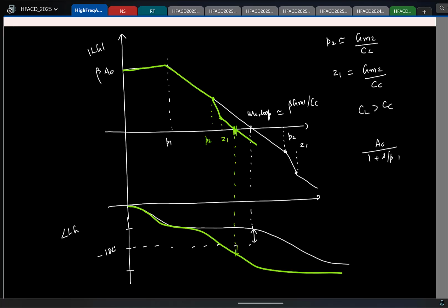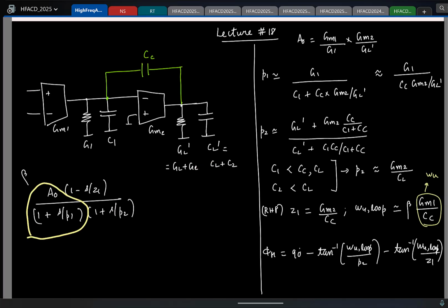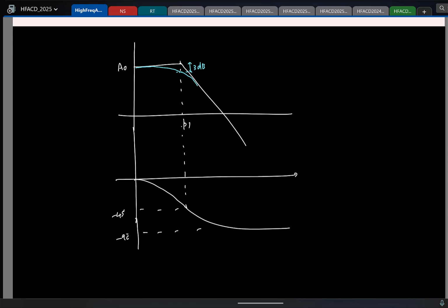So hopefully till this point things are clear. So if you are now comfortable with two-stage Miller op amp at block level, now let's get into transistor level details. So first I have to have the first stage that takes in two inputs, amplifies the difference and gives a single-ended output. What circuit can do this? The 5 transistor OTA. So let's first sketch it. Again, we can have the 5 transistor diff amp using an NMOS input differential pair or a PMOS input differential pair. I will sketch with an NMOS input in the class, but we can take it as an exercise and try to sketch the same with a PMOS input version.